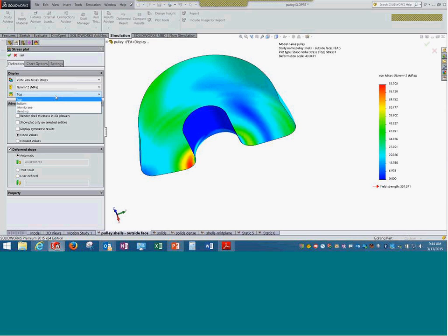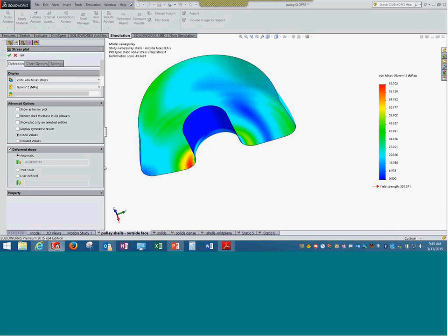Second, sometimes, especially if it is a thick shell element, ensure you check these things. It may be a case wherein the top stresses are lesser, but the bottom are more. In some cases, membrane stresses are far more important than the bending as well. So you might want to scroll through all these stresses to check which is more. You can also do an initial judgment, think which could be more, and then directly jump onto that particular stress. No issues on that. This is how it is.